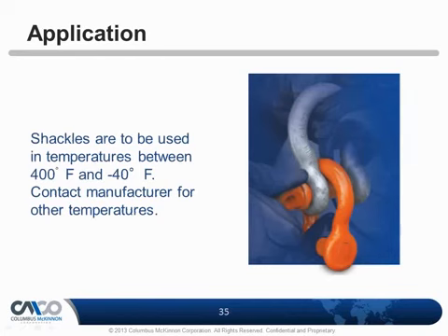Shackles can be used from 400 degrees Fahrenheit down to -40 degrees Fahrenheit, and if you go any temperatures beyond those, contact the manufacturer of the shackle to see what the rating would be used in those environments.